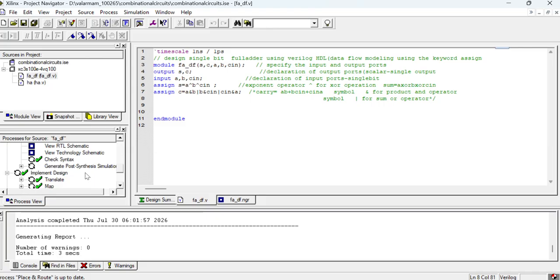Next I will tell you how to write a test bench for our design, the half adder and full adder. I have written the code, and I have to test it. I have to verify simulation and synthesis. These two words, simulation and synthesis, are part of the design flow. Synthesis covers the backend process: floor planning, placement, routing, and how the physical layout is dumped into the device. Here we have chosen the target device Spartan 3, and that part we have done using this tool.